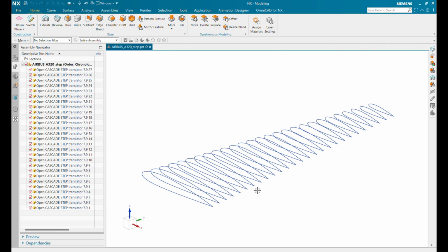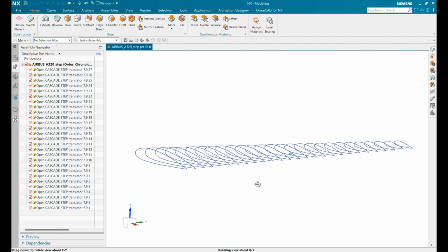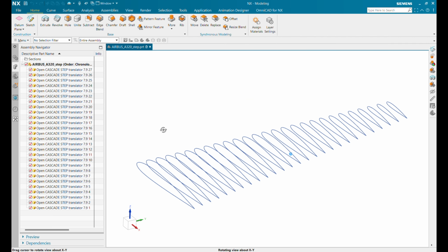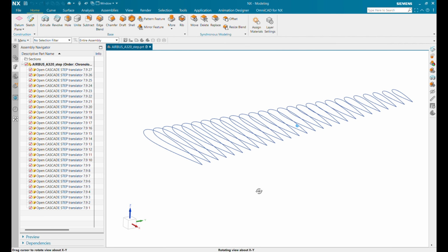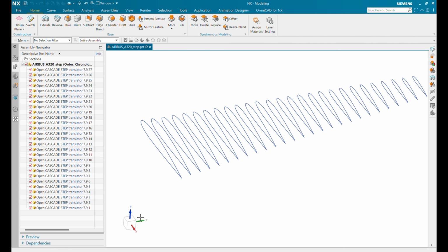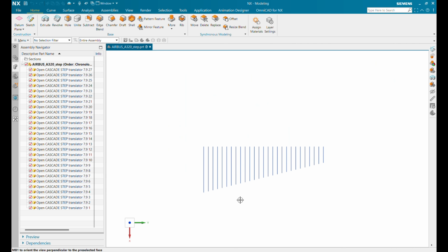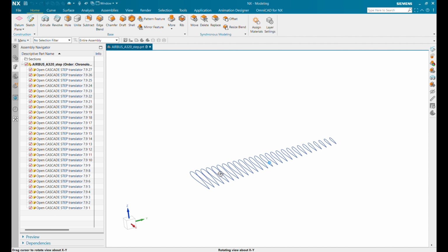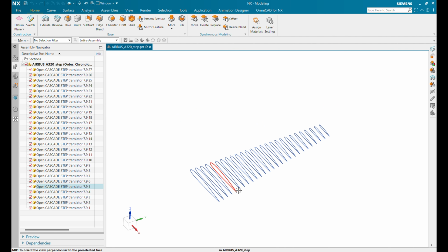Okay, so what you see here is that we've got the profile for the airfoil for each of the different 27 ribs, spanning across 16.955 meters, with the starting chord length of 6.5 meters, tapering down to 2.3 meters at the end of the wing's tip.